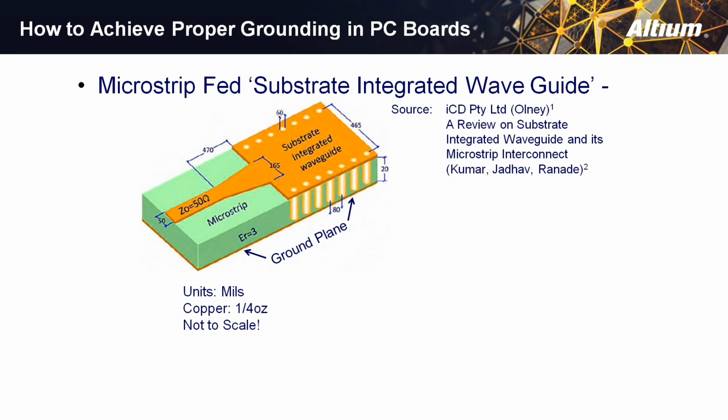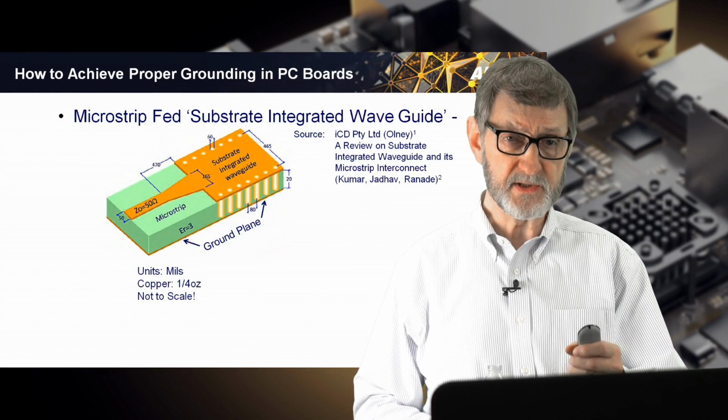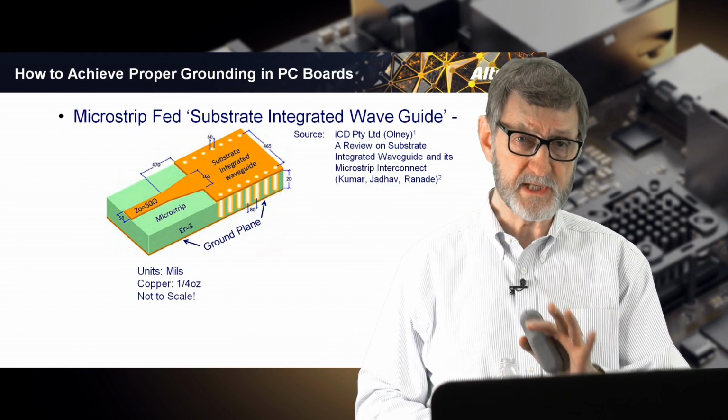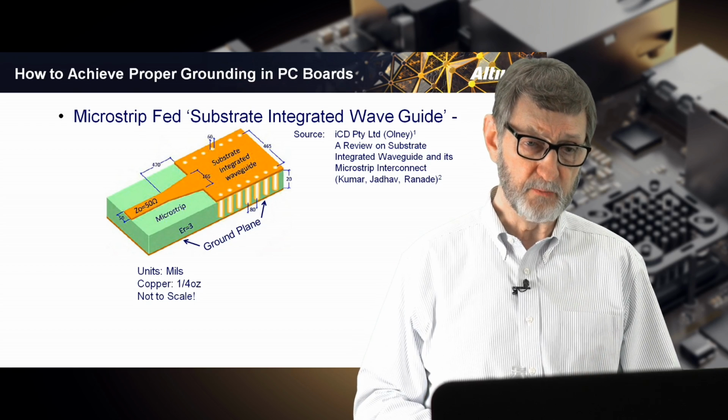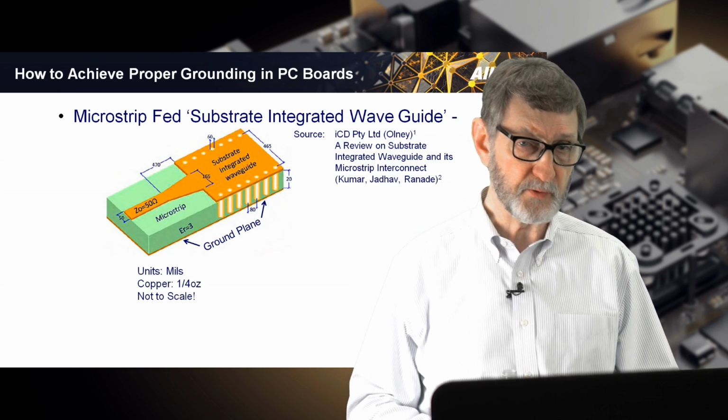This too is a waveguide. It's a waveguide that's built into a circuit board using circuit board material and the copper of planes. In this particular case, the waveguide has a slower movement of energy because the higher dielectric constant slows the energy down, but it still functions in exactly the same way as the air dielectric tubular waveguide. The energy launched into this will move through it one frequency only, just as it did with the tubular waveguide. Notice that feeding this is a microstrip trace.